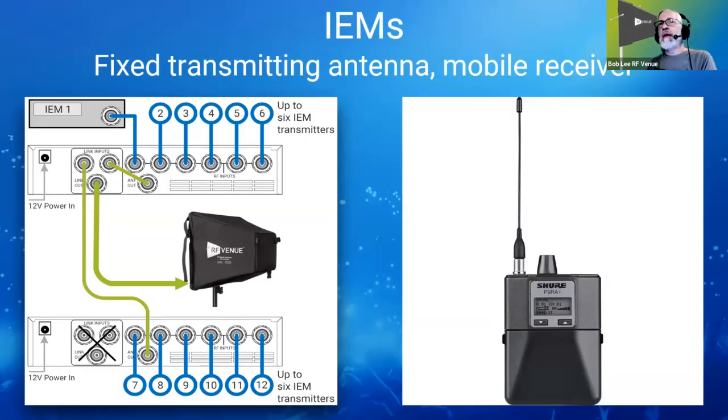So now we're going to get to what I call side stories. These are just little tidbits that give you a little illumination of the whole system. Now, first, I'm going to go into the little messages that mic transmitters send to their receivers. Not all of them do, but some of them do, and it can really help you out when you're operating a wireless mic system. First is squelch tone, also known as the pilot tone.